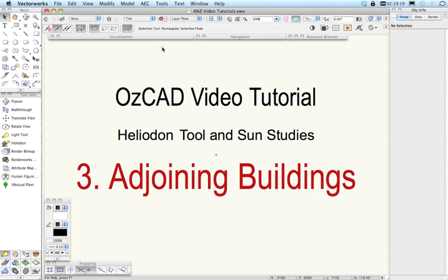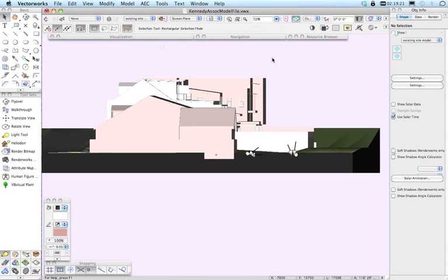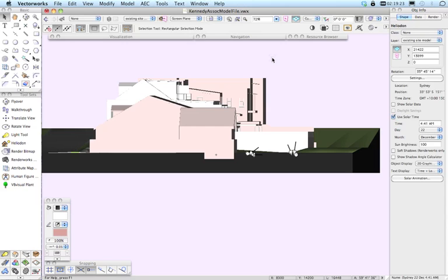So let's switch to the model that's been given to us by Kennedy Associates, and this initial view is at sunrise in the summer solstice. You'll notice here that I have use solar time checked now, and when you check this option, daylight saving is taken out of the picture.